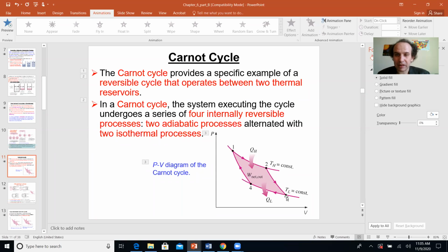Okay, the opposite example. I have a piston cylinder assembly. I push the piston down. Let's assume my system is insulated, no heat transfer. I push the piston down and my mixture may heat up and may even explode. So, is it adiabatic? Yes. Is it isothermal? No. The temperature will change. So, I remind you, a Carnot cycle consists of two adiabats and two isotherms.